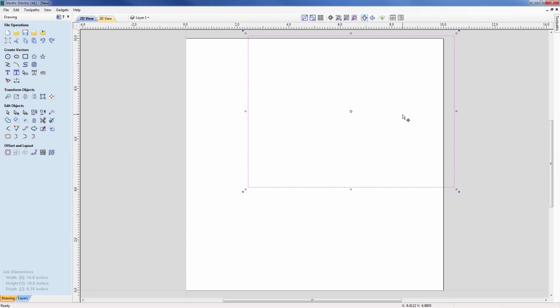So there we've looked at all the scaling parameters, and now we're going to move on and take a look at rotation. So I'm just going to hit Ctrl Z to bring it back to its original size. And you can see in the top right hand corner of the transform mode, the rotation anchor. So as I rotate this, you can see I'm going clockwise or anti-clockwise, and the angle that we specify will always assume anti-clockwise. So even if I'm moving in the positive direction and enter the value 25, it will be rotating this counterclockwise by 25 degrees.